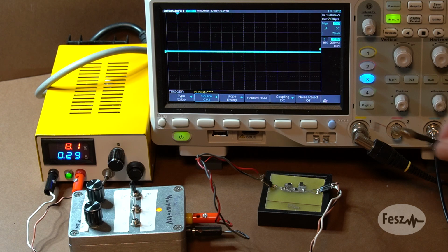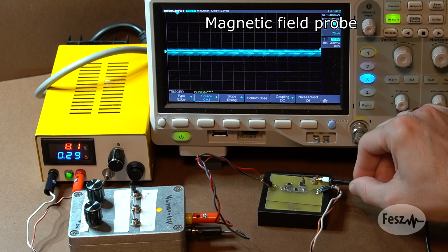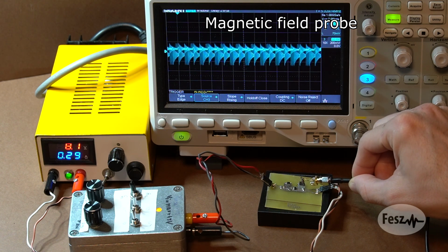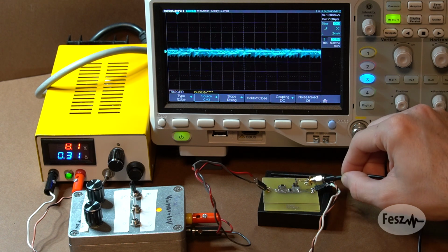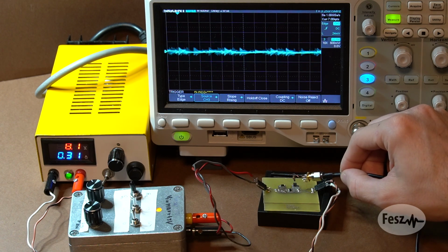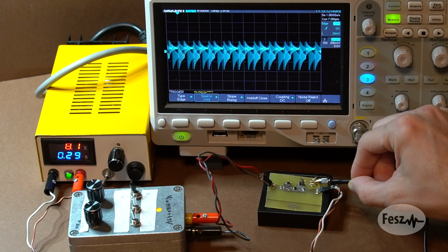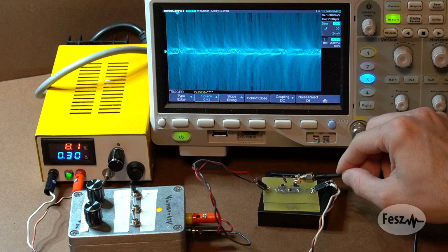Now, while observing the current in each branch of the power supply is a more challenging measurement, what is a bit easier to do is to measure the current-generated noise in the form of a magnetic field noise, which is present around the various converter branches. So with this design, when my magnetic probe is close to the triangular currents in the input and inductor, we are getting a certain amount of noise. However, if we look over the switching components, the noise increases dramatically.